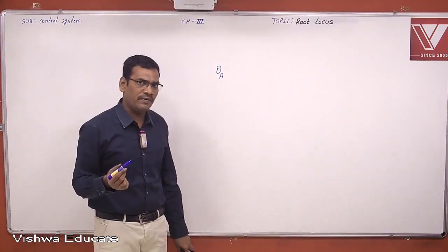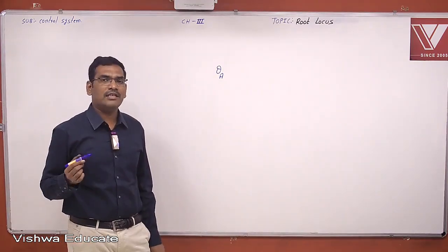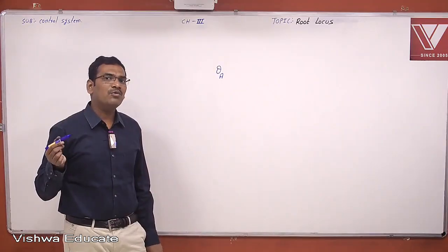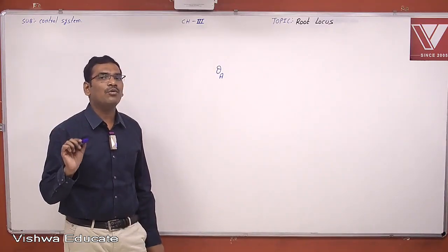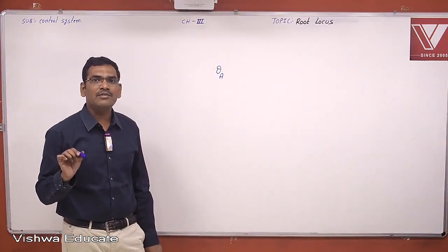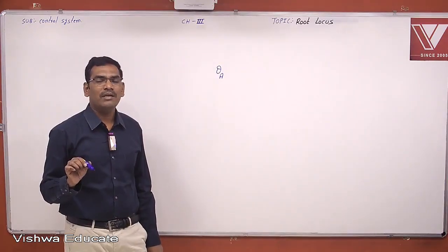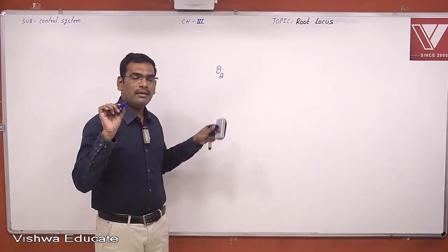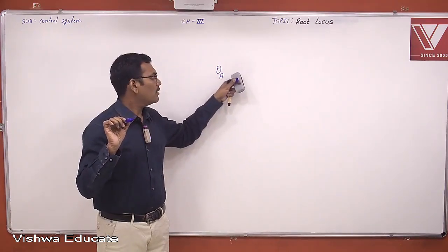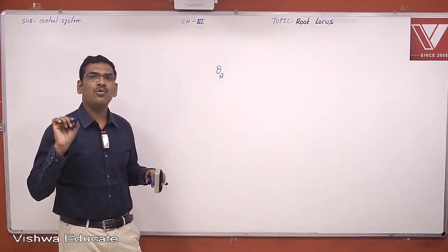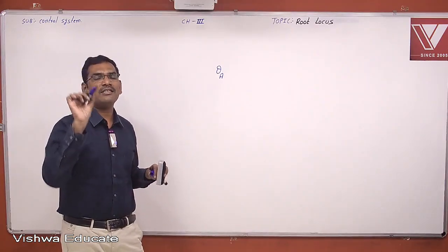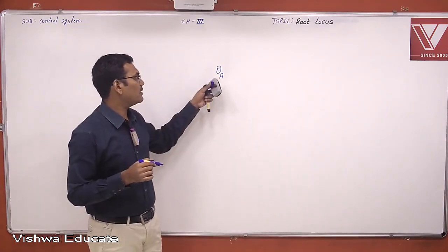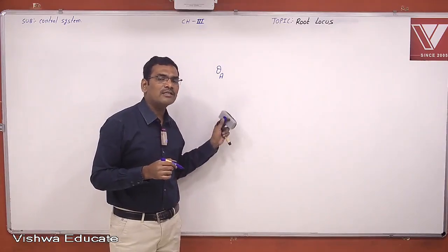We are searching for 0, right? Generally the root locus diagram ends at k equal to infinity and ends at the open loop 0. So the angle of asymptote is the direction showing where the root locus branch is terminating. The angle of asymptotes are the root locus branches which approach infinity.